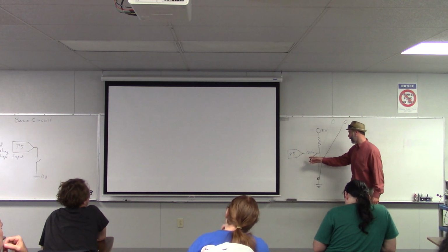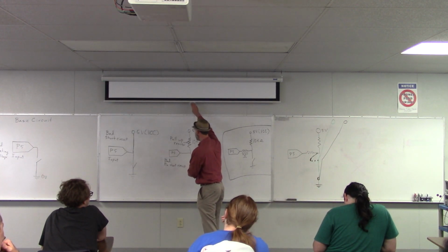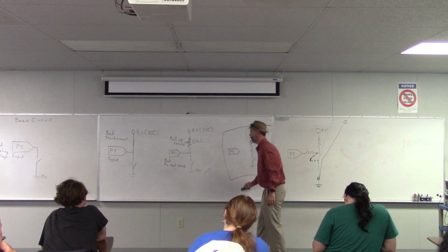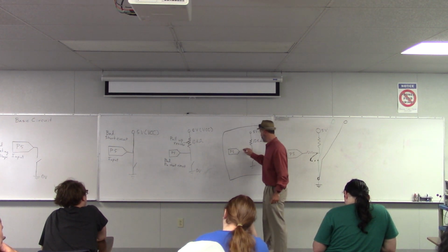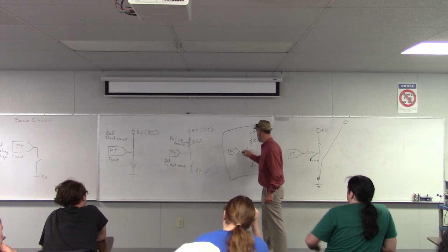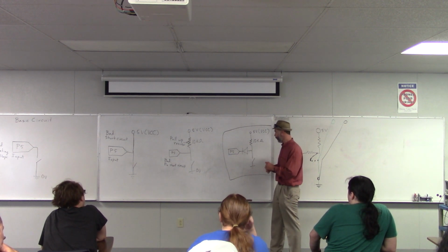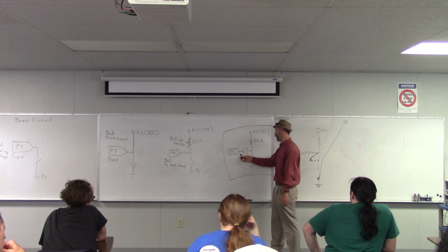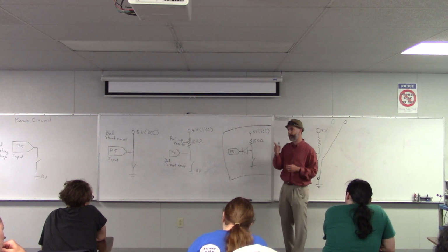Basically, what happens is that if you had a diode here, like you mentioned, it would protect this pin because if you made this a high voltage, then this would block any of that voltage from flowing down to ground if the switch was closed. So that would be great.